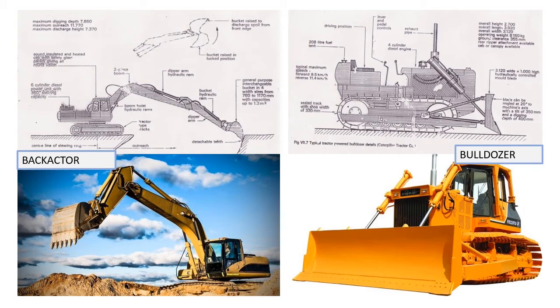Backhoe used in trenching operations with a bucket width equal to the trench width can be very accurate with high power rating. For Bulldozer, this machine consists of a track or wheel-mounted power unit with a mould blade at the front which is controlled by hydraulic rams. Many bulldozers have the capacity to adjust the mould blade to form an angle dozer and the capacity to tilt the mould blade about a central swivel point.